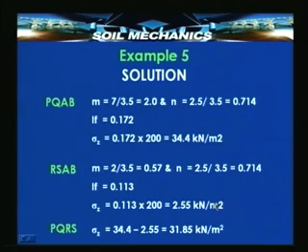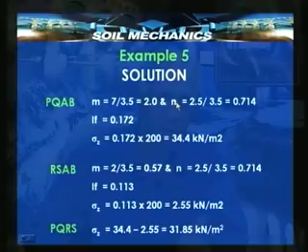The solution is, first take the larger rectangle, compute n, determine the influence coefficient from the influence coefficient table, because the influence coefficient table that we use for rectangular areas have m and n values ranging from 0 to infinity, and therefore, they cover the entire range of m n values that are feasible or practicable.